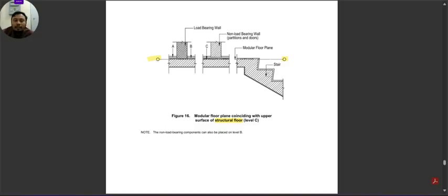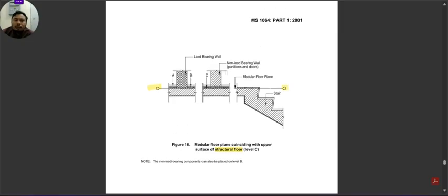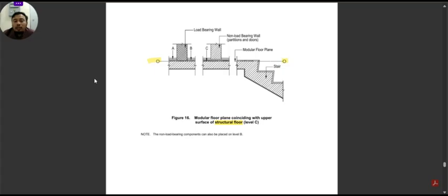So this can be set earlier on so that your vertical components, like something stacking, like a wall panel that is stacked, or a window panel, curtain wall, something in the wall height. So when you decide it, you need to know if the component has been chosen. So the vertical component defines how you design the component. The vertical coordinating dimensions define your wall panel height, your windows height, door frame height. Because if it is within the modular, the wall component can fit perfectly.